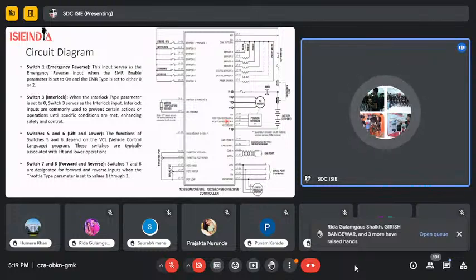So what is the purpose of the sensor? To detect the position of the rotor and give the response to the controller, and as per that response only, the power should be delivered by the battery to the motor through the controller. So the main function of this part is to get the response from the encoder to rotate the motor.